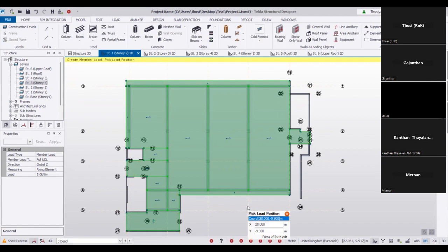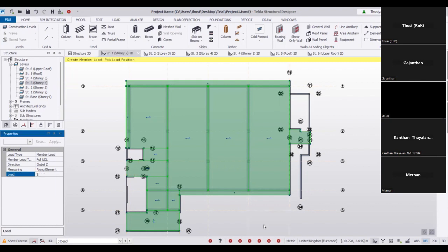So it's approximately 2.2 to 2.4 kPa in the vertical elevation. It's a 4 meter height, so I assume 2 kPa into 4, which is 8 kilonewton per meter. So I take 8 kilonewton per meter, but you can calculate exactly.